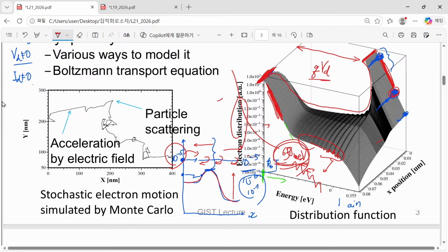The more exact value is 63, or 61, sorry, I don't remember exactly, and this energy is related to the most representative phonon energy. Inside our silicon system, there are so many phonon modes that interact with electrons, but among them, the most efficient, most active and most profound one corresponds to the energy of 60 milli electron volt.